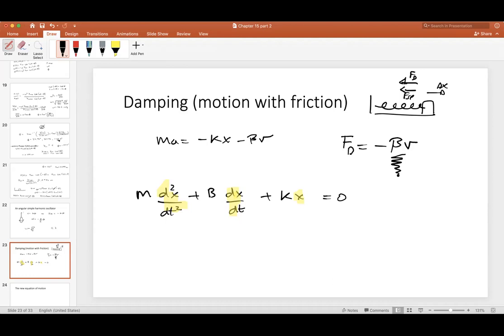This is a lot like what we did for air drag way back, chapter 4 or 5 or wherever we did that. I think it was 4. So it's a super simple model. If you can model the drag force on it as some number times the velocity, you've got a drag force. You've got a damping force. Some frictional force is what that is.